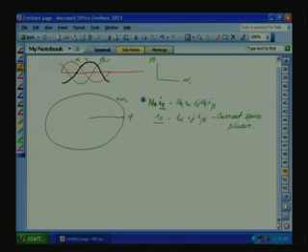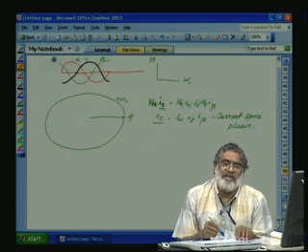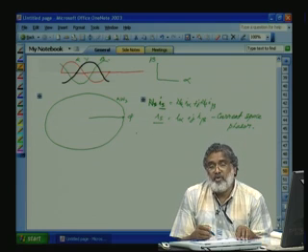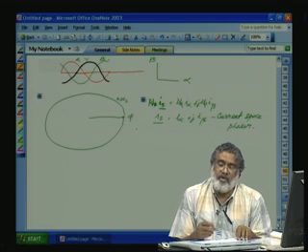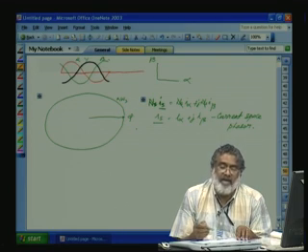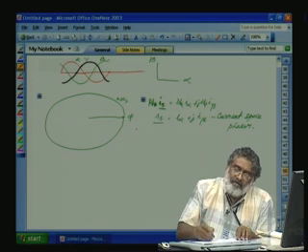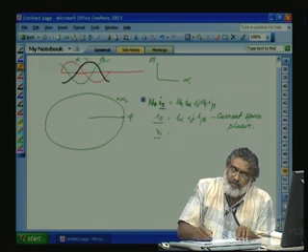This current is produced by the three currents IA, IB, IC. This is also the current space phasor. This sinusoidal current is flowing into the machine due to the excitation with sinusoidal voltages. That voltage and current will have a phase angle of phi. So, we can also have a definition, an equivalent voltage space vector, V alpha plus jV beta.